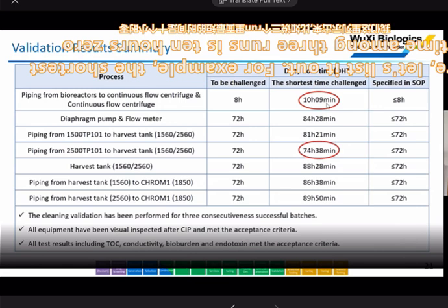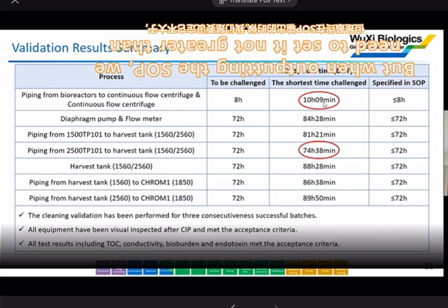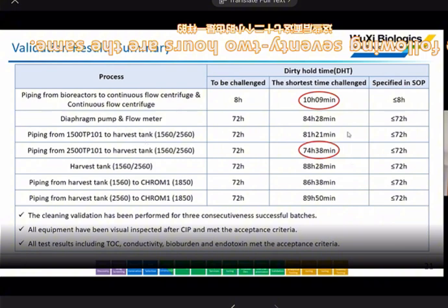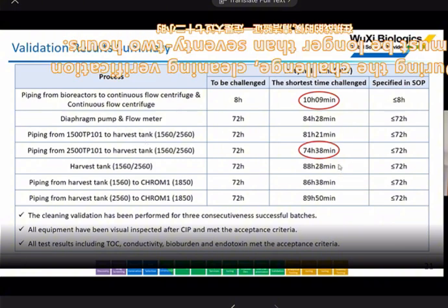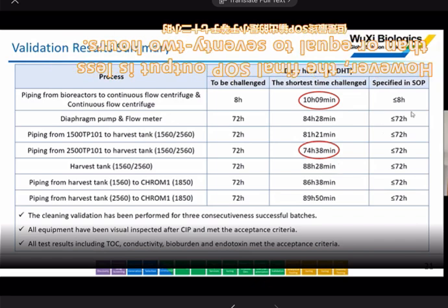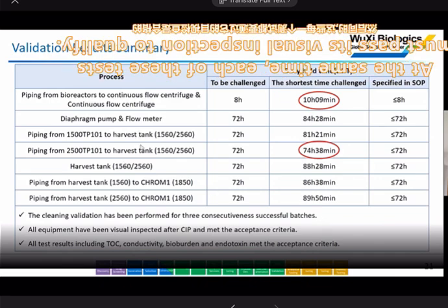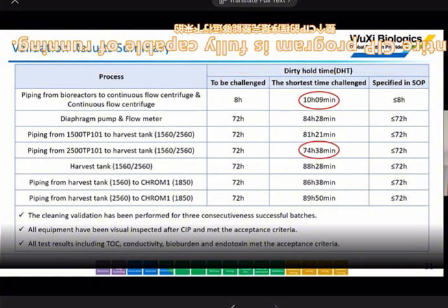As for some limit calculations, which I just mentioned, you need a 1/1000th of a daily dose of material and 10 ppm, including PDE data. This calculation uses 3 methods, taking the lowest value. Then, conductivity, bioburden, and endotoxin, which can be customized according to process requirements. However, many times it is only WFI standards that are selected. However, this can also be tailored according to process requirements.